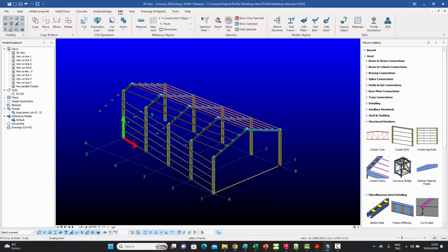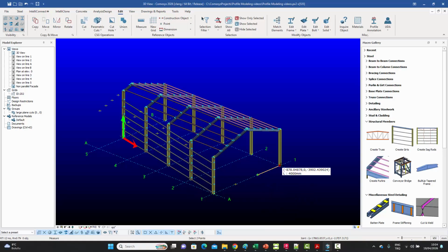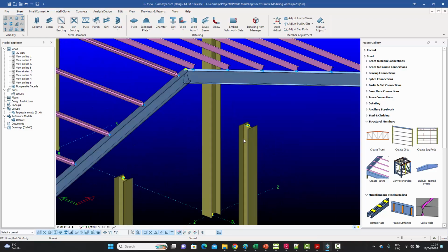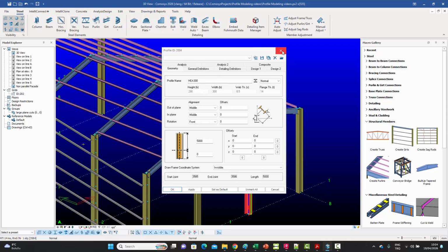So before you click on that, you press 2 so that you get 2 points created in the middle, and those should now be at a distance of 4 meters from the sides, like that. 4 meters between them as well, and 4 meters to the end over here as well. And now we can enter basically the steel columns over there. We need to, let's undo that. We need to bring back the work plane to the global, because these commands always work in the local work planes. Click on that, click on that. Make sure the direction is correct. Yes, the direction is correct. Make sure the profile is correct. It's HEA 300, that's fine as well.